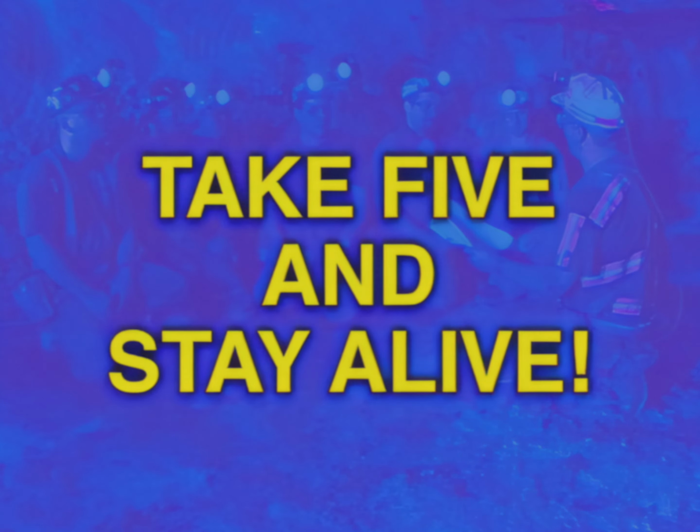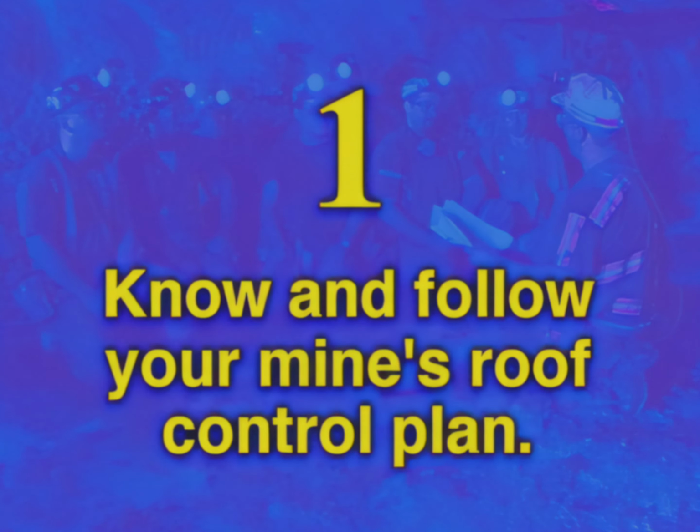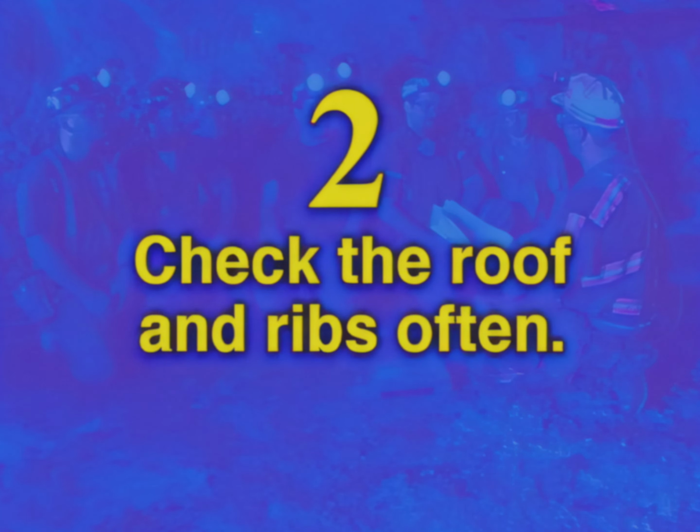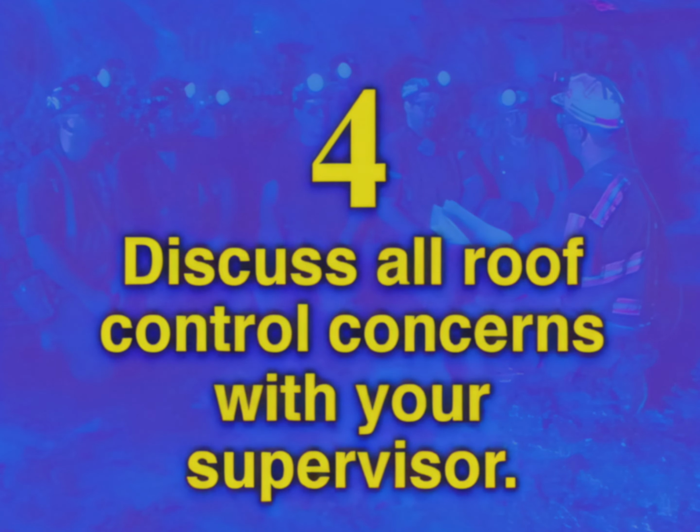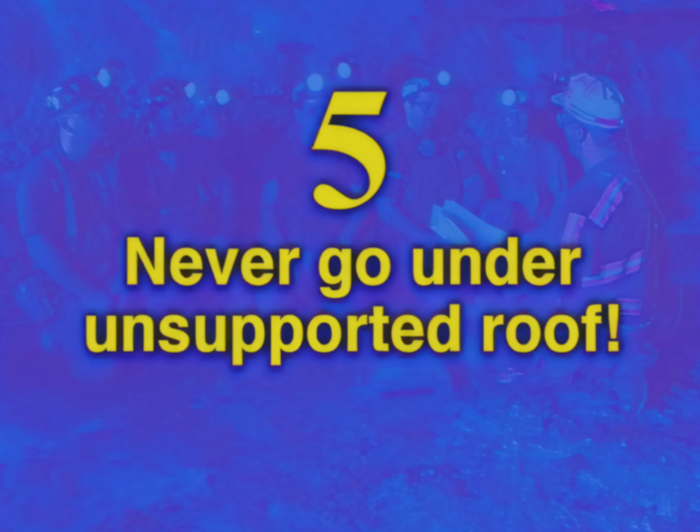Remember, take 5 and stay alive. Know and follow your mine's roof control plan. Check the roof and ribs often. Be aware of your surroundings. Watch for changing conditions. Discuss all roof control concerns with your supervisor and never go under unsupported roof.